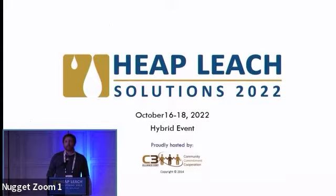However, at Dolores, we did install a mixer, which looks like a mineral sizer almost, but a little bit different on the insides, where they just blended the cake. The primary reason for that was to break up the filter cake a little bit more before it gets to the drum. That way you don't have big clumps of filter cake that doesn't get properly agglomerated.